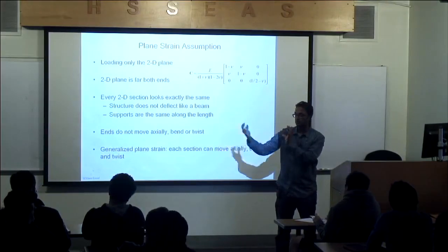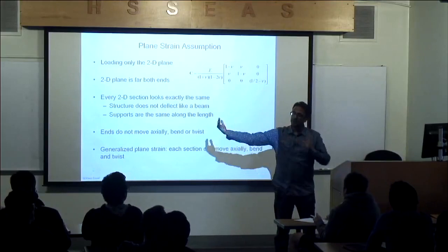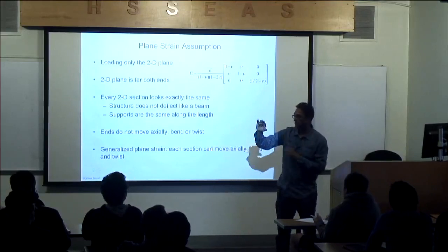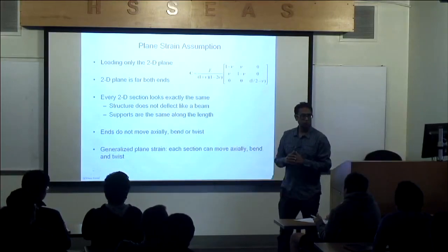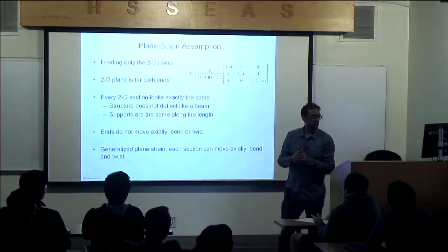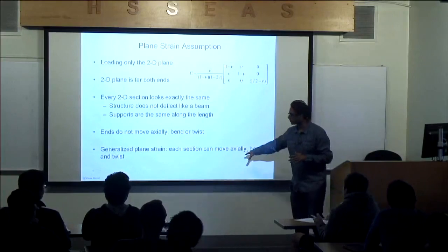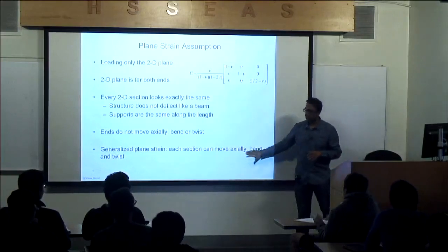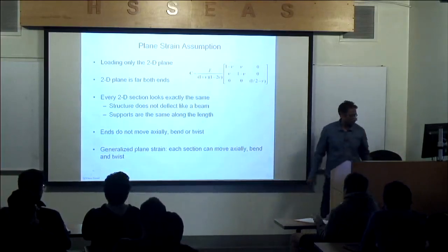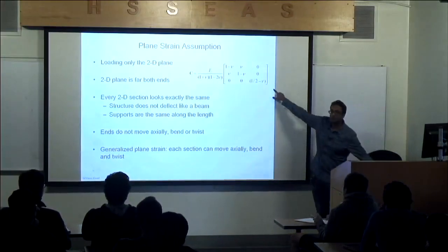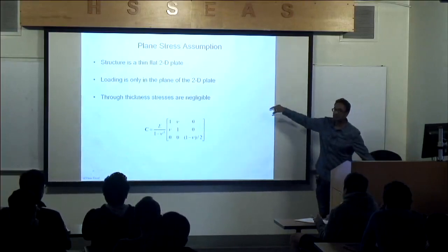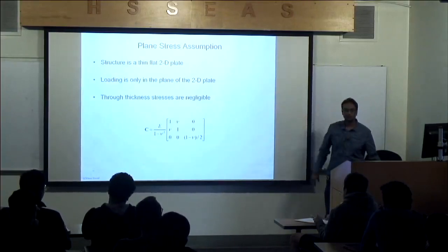It's incredible. You can apply bending and out-of-plane loading, not just in plane. So they were able to extend that formulation further. I've used that formulation quite a bit, so just keep that in mind. You can do that. This element here is the CPE4 in Abaqus for quadrilateral, and for plane stress it is the CPS4, I believe.